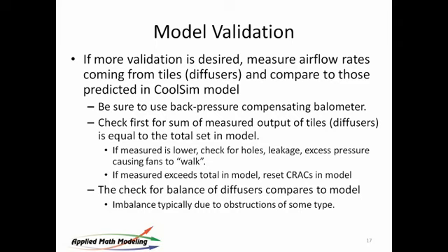First, look at the delta T's on the cracks and make sure they're valid. Then take a look if you want to go further. Oftentimes, delta T's on the cracks are enough, because you've captured the physics. You're just looking for rough parameters. You're trying to get your hands around the big things. But if you want to go further, then measure the flow rates. And first, the totals need to match. The total being measured needs to equal the total being delivered in your model. And then look at distribution.